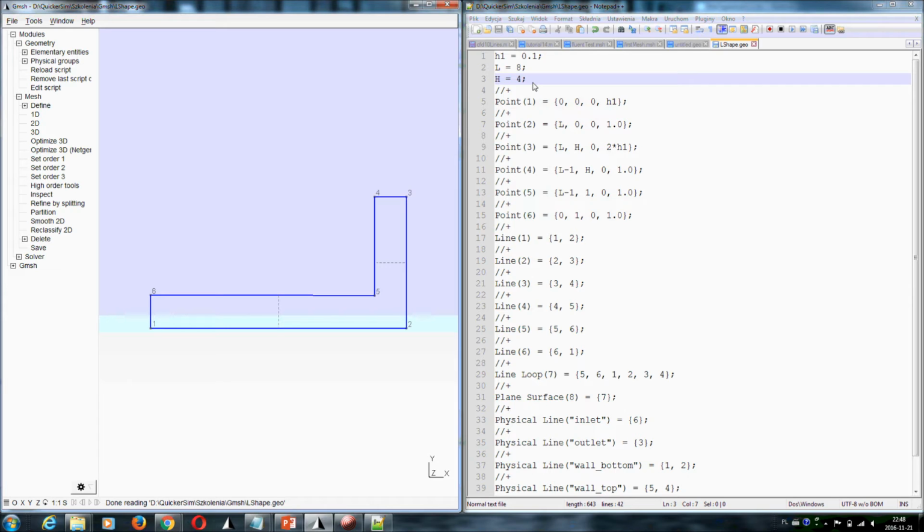You can run this for example with MATLAB optimization toolbox and solve the fluid flow or heat transfer problem in QuickerSim CFD toolbox for MATLAB, or in every other solver where you can use your meshes. All right, let's try to generate the mesh once again. Of course, our specification of element sizes is retained, so nothing has changed here.